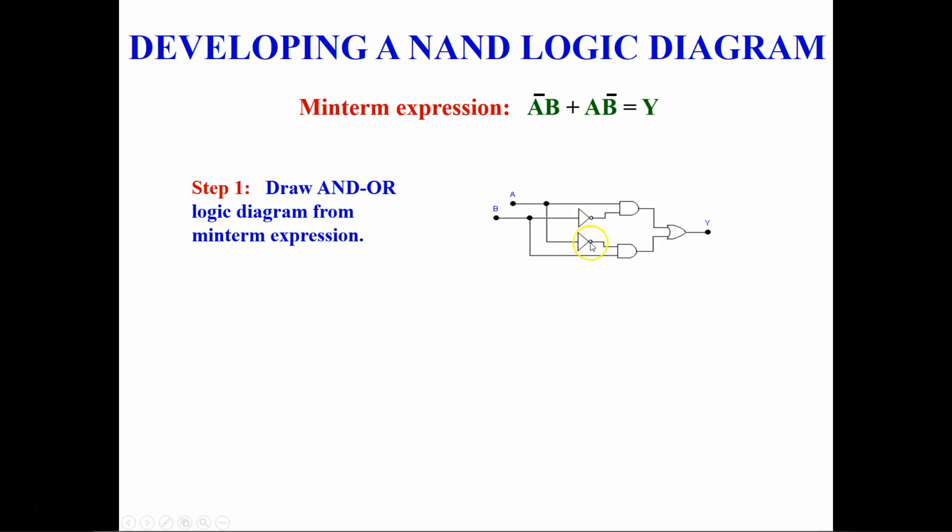So that's why you have a NOT gate here, because if it goes through this, it will become A bar or A complement. So A complement will go into this AND gate, and then this B is going in here, and then similarly here that B is going through the NOT gate, so B here is going to be complemented. So B complement will go into the AND gate, and A will directly go into the AND gate, and then here they will form.